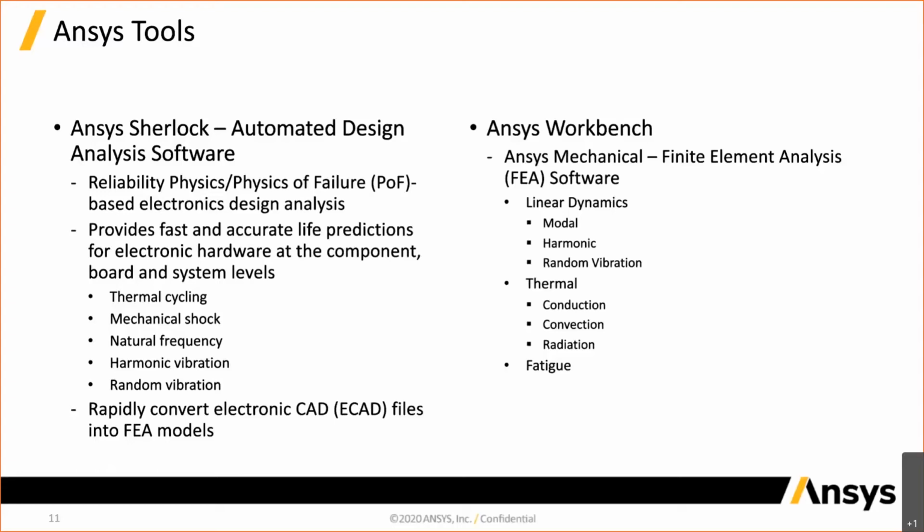But if you don't have Sherlock, or maybe don't want to use those internal Sherlock tools, Sherlock can also be used as a front end to any type of FEA engine. For Ansys, we're going to use Ansys Workbench. I typically will build the PCB model in Sherlock, and if I have to do something else to it, I will export or translate it. I hit a button, it automatically opens up and generates a Workbench model of the board, so you can do other FEA type stuff to it. I'm going to do a natural frequency study. I'll do it first in Sherlock, then I'll show it in Ansys Workbench.